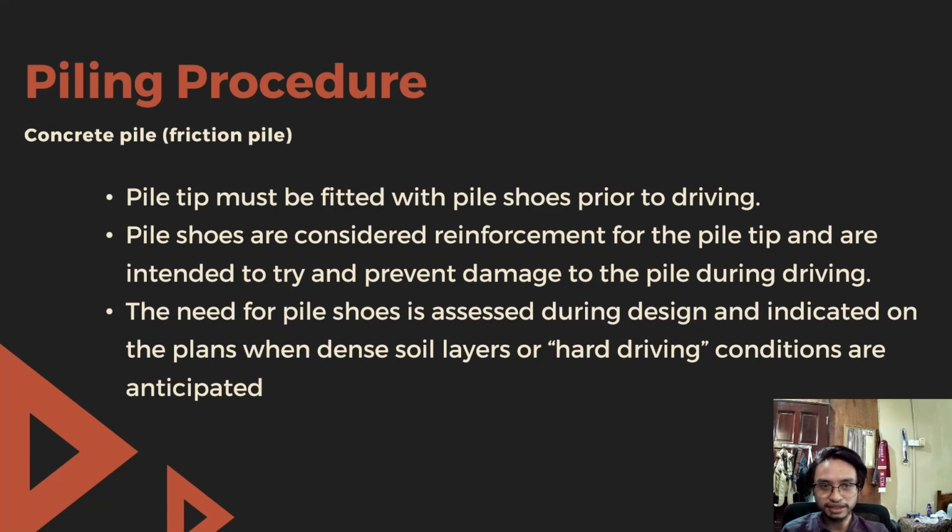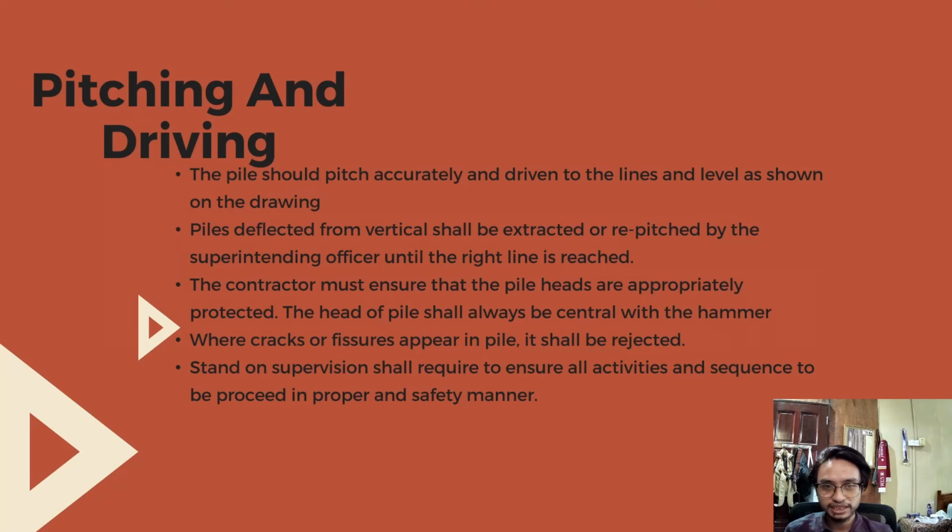Next is piling. The pile used in the case study was a concrete pile. So I will talk about the piling procedure. The pile tip must be fitted with pile shoes prior to driving. Pile shoes are considered reinforcement for the pile tip and are intended to prevent damage to the pile during driving. The need for pile shoes is assessed during design and indicated on the plan when dense soils or hard driving conditions are anticipated.